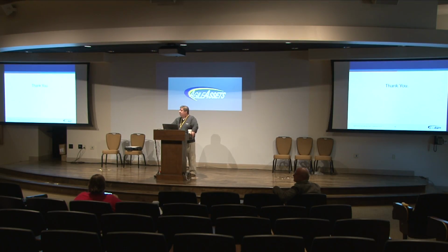That's not going to help the measures in the middle of the route, but it would ensure the measures at the ends of the route are rounded to 2 or 3 decimal places. It's not going to add decimal places. If you explicitly state a measure value, it will honor that, but it's going to use that to interpolate up and down the route. If you put them at the end, at least when you ask for the measures for the entire route, it'll be 0.0 and 26.314.